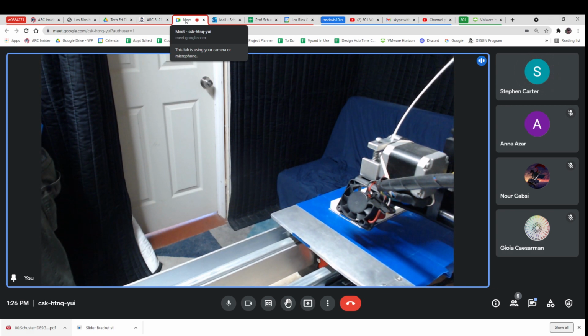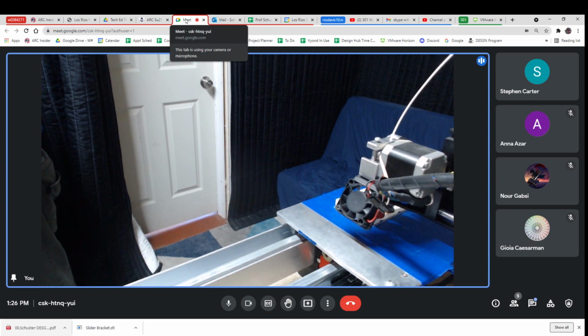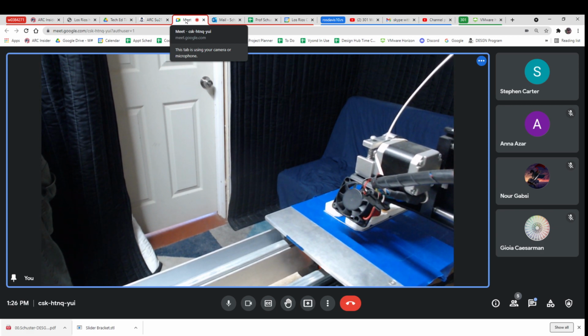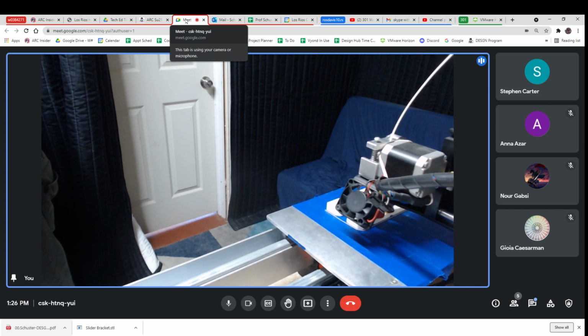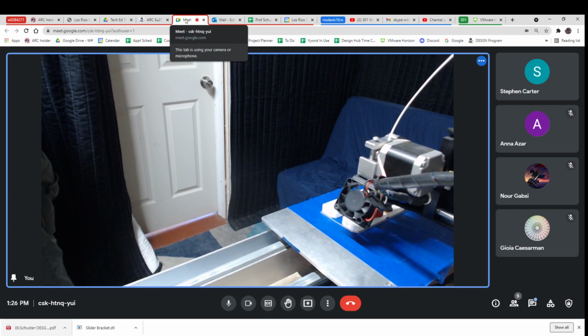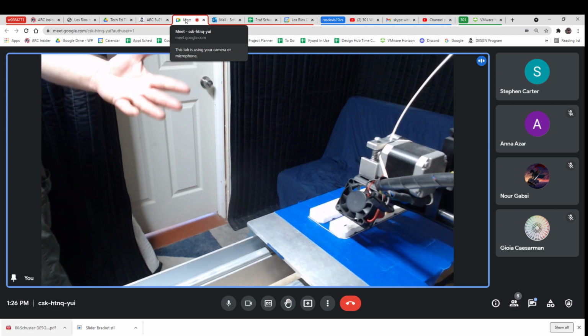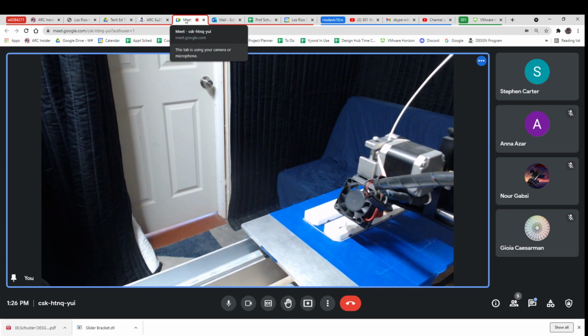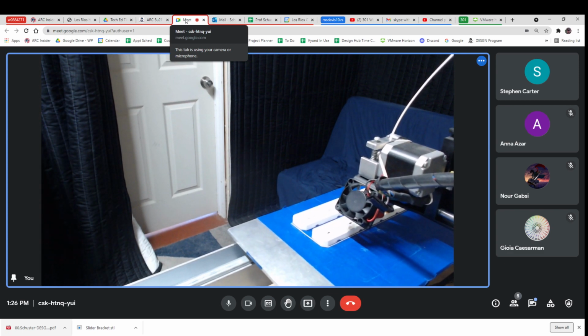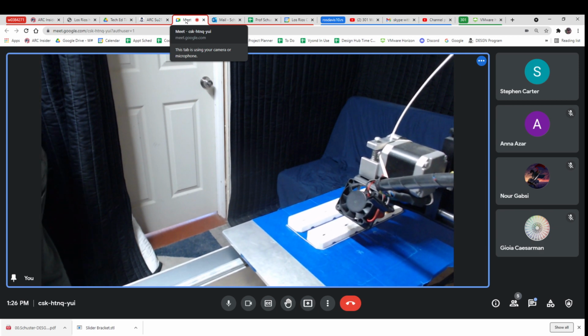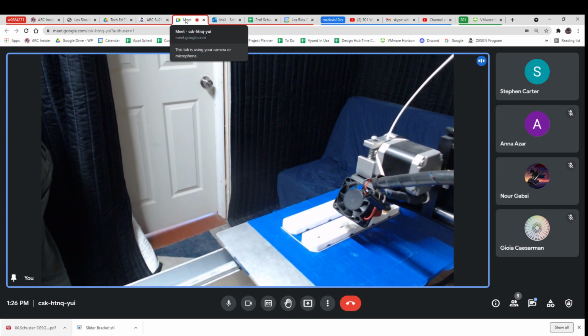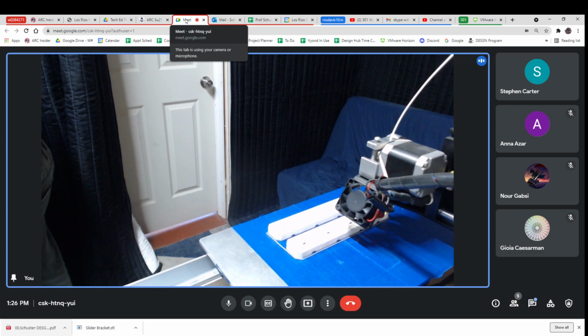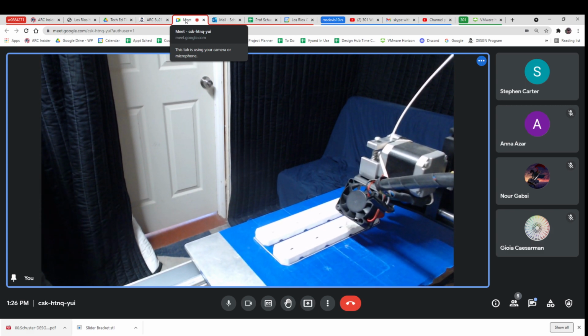It's got just enough stick and bump so that when you put it down, the filament sticks. And it's awesome. And then if it does come up with the part, I just, a roll of tape lasts me 3 or 4 months for $6. If you've got a heated bed, of course, you don't need that. It kind of stays down just because of the heat.